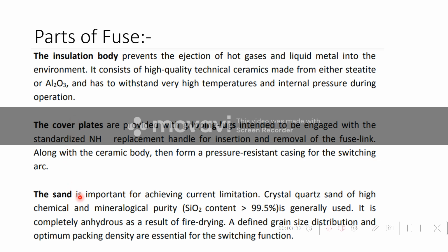The sand is also very important in achieving the current limitation, because when the fuse blows out, or when the fuse element melts, the melted components are settled down or absorbed by the sand, and that heat is dissipated to the outside atmosphere.